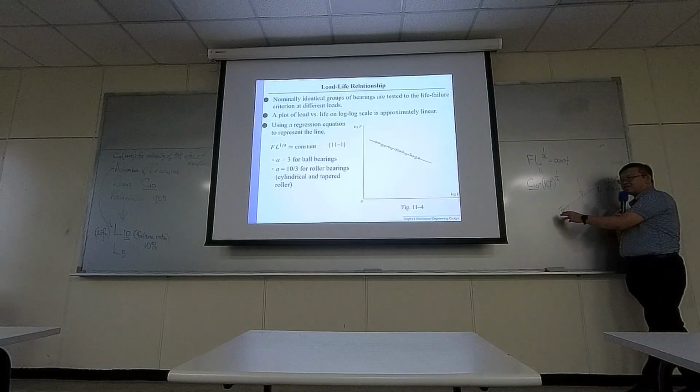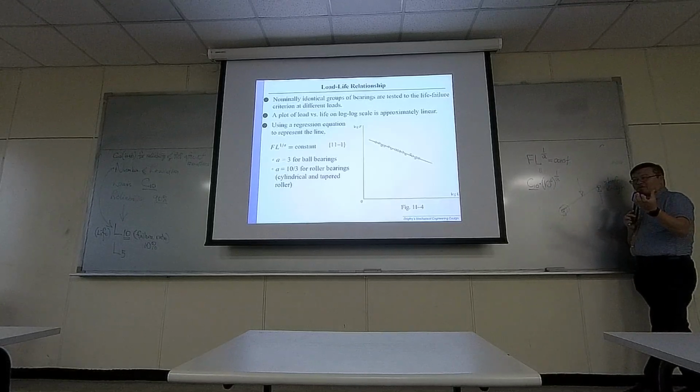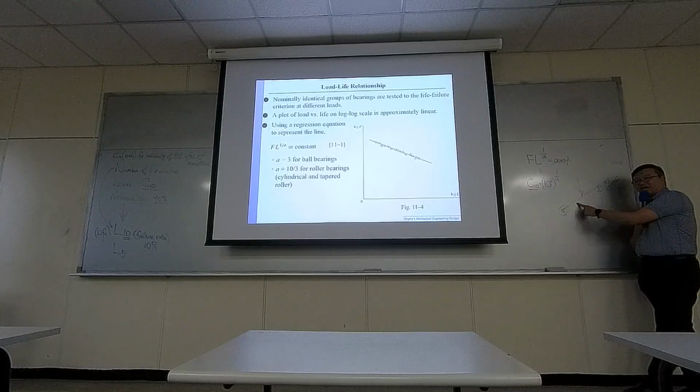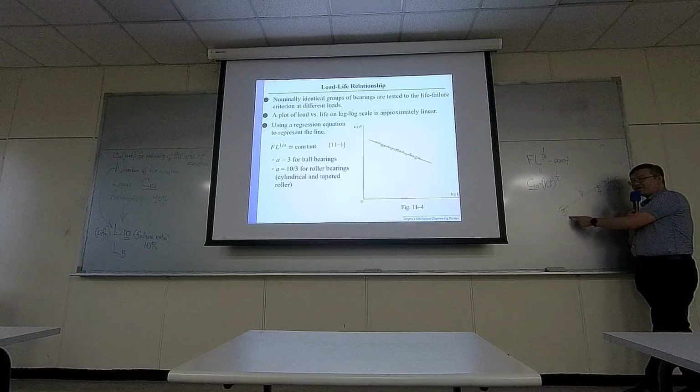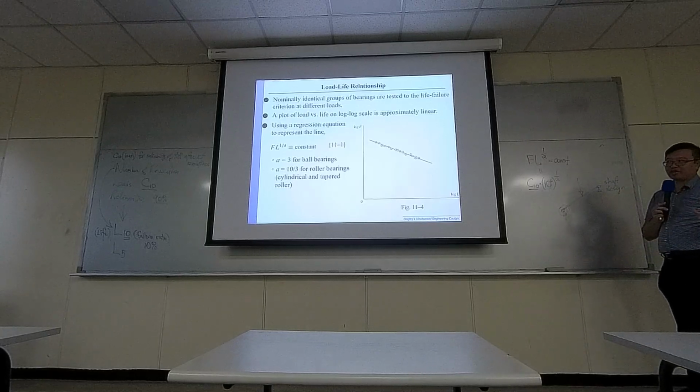But once you pick a proper bearing, maybe the bore dimension is not matching what you had earlier. So you will be making changes back and forth because they are so tightly related. So that's one way.